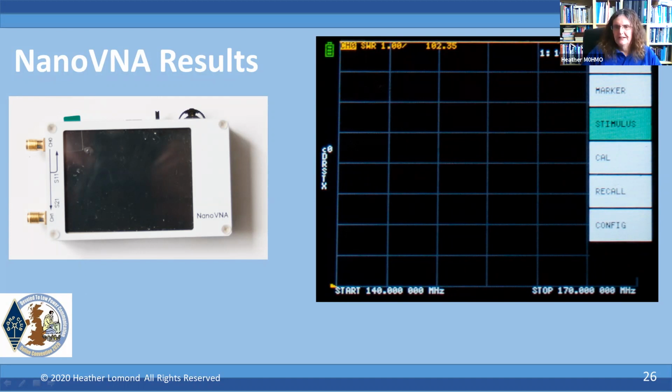So yeah, it's quite easy to do. People make them out of these clip-on ferrites where you can just wrap a coil around that. Plenty of designs online, but they're essential to really measure your balun and make sure that you've got a balance in there, to measure the common mode signals.